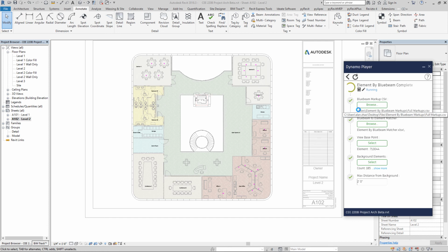For the level 2 markups, it's going to read the markups as label 102, and it's going to filter out those ones we already set to complete, so that it doesn't create duplicate elements on top of each other, but it's going to try to create the rest of them, and again, try to snap them to walls when applicable. But for those ones in the center of the desk, hopefully it's not within 2 feet of any wall, so that it's not going to be moved.